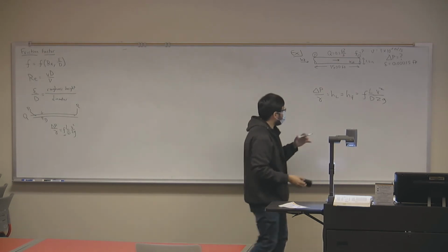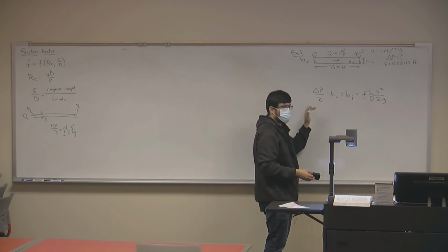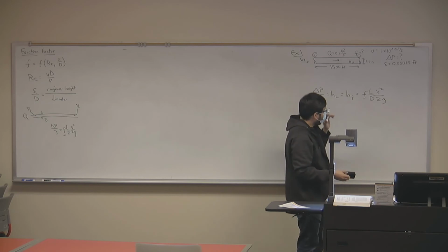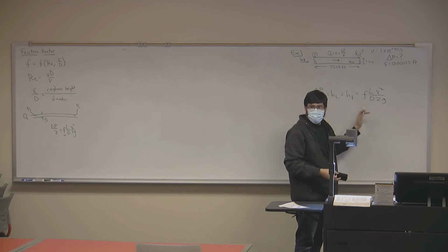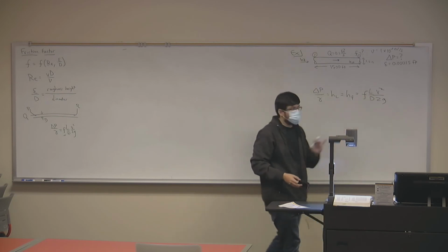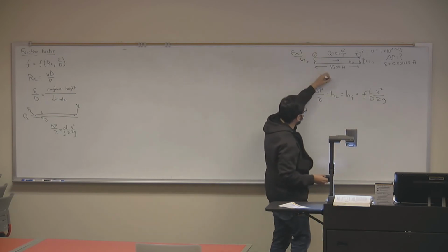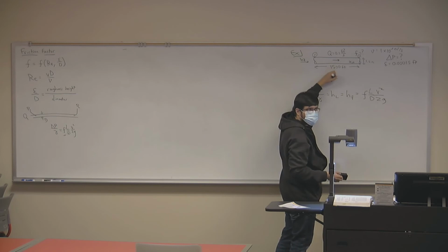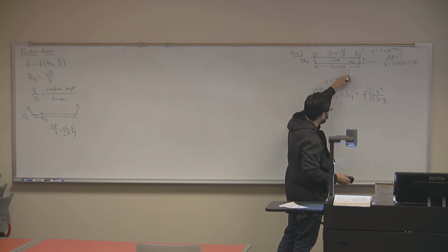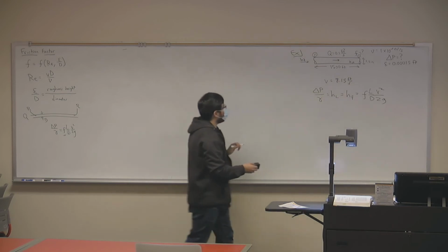But now, let me say, we want to find pressure drop. Do we still know gamma with the changes we made? Okay. Do we know friction factor with the changes we made? No, but we can calculate it, right? And then everything else remains the same, okay? So let's recall that velocity was, is it 8.55, 8.15? 8.15, okay. So we do have that velocity, that doesn't change. But now let's find that friction factor.